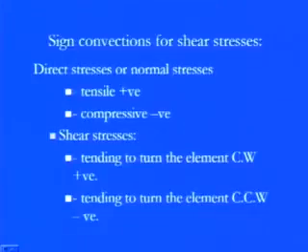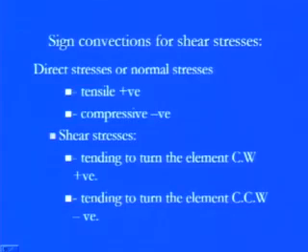Positive and negative apply to the direct or normal stress, and for the shear stress, if it tends to move the object in the clockwise direction, consider it positive. And as we have seen in the previous case, the complementary shear stresses, which oppose that and try to rotate the object in the anti-clockwise direction, are considered the negative direction.